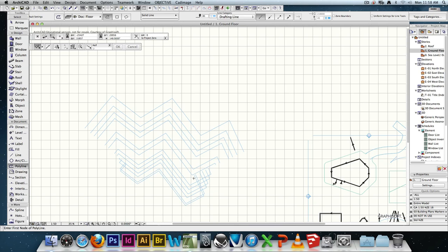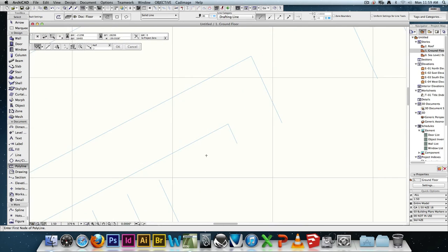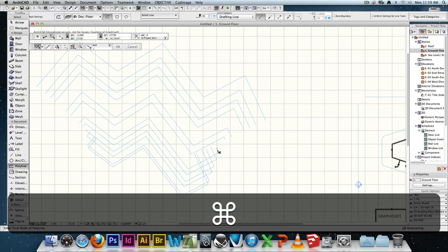It's just offsetting everything. So when I got to this point, what I would probably do is stop, delete that, and then keep going, because I don't need this edge anymore. This edge just doesn't make any sense anymore. I can just go and trim those off. Maybe I want to keep those bits. It's just holding down the command key and trimming off what I don't need.